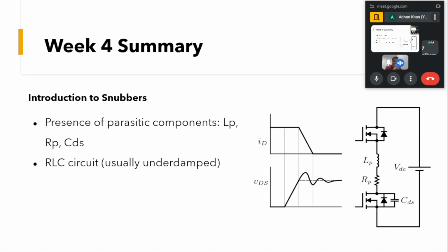We know that till now we had seen the ideal cases, but in the non-ideal cases, we have some parasitics there because of the leads and power traces. If we have some leads, they will have some resistance and some inductance, and if we have PCB traces, there will be parasitic resistance and parasitic inductance.